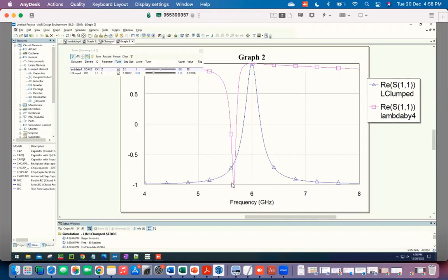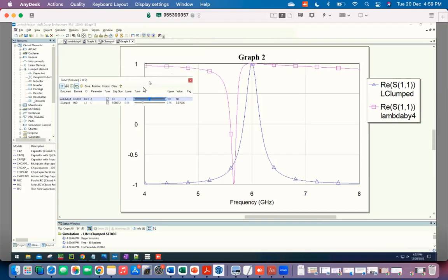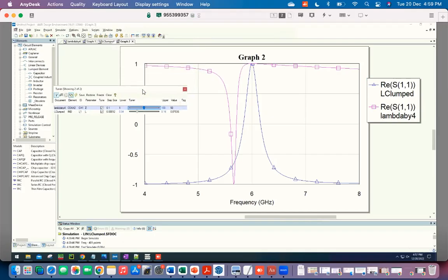If we now identify this as the resonance, because in this case this was the resonance, it seems to have gotten inverted in phase, because now minus becomes plus, plus becomes minus. There is some little asymmetry here as well. Now all of this is due to the capacitance. Let's first look at the line width, which has become narrow, which was the only effect we were hoping to achieve with this.